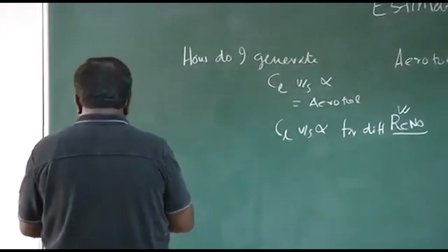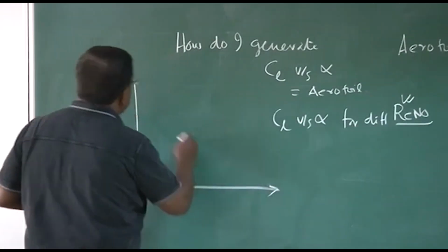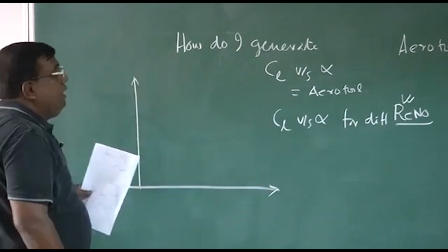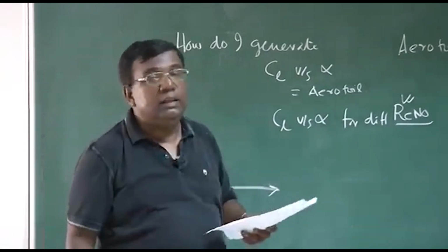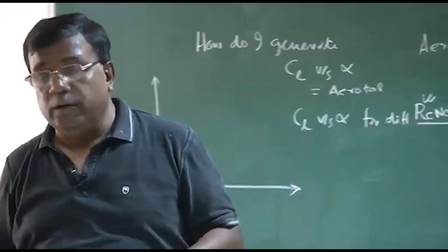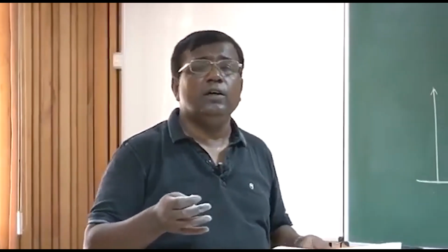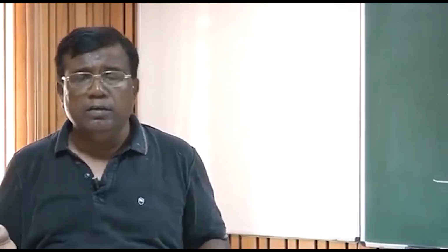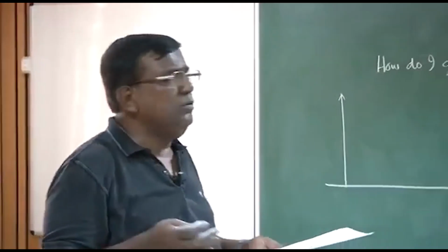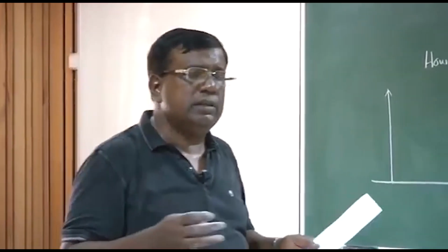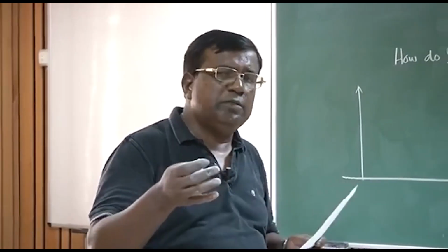So typically, if you see a database of aerofoils which will give you the CL, CD characteristics for different aerofoils, they are being generated through experiments. And each aerofoil is named depending upon its nose radius and its thickness to chord ratio. There is a standard nomenclature. We will try to address that nomenclature before I come to some aspects of design.